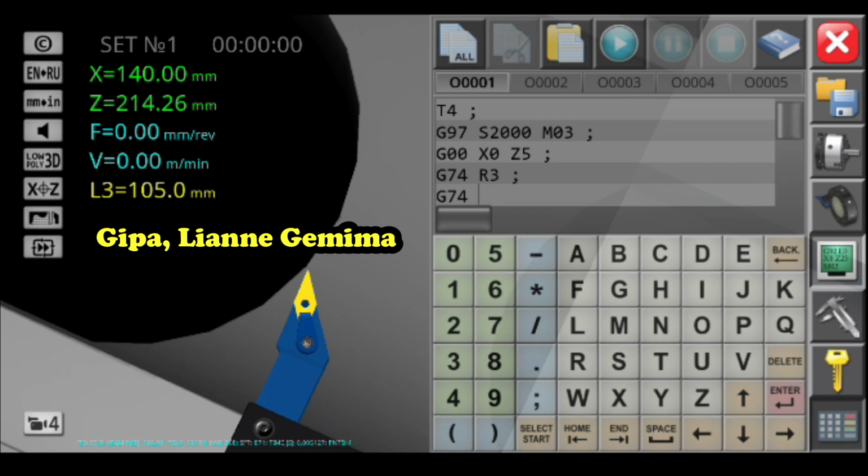which stands for the end face spec drilling, Z-75, Q10000, and F0.3. Next is G28, and then M05 to stop spindle rotation, and then M30 to end the control program.